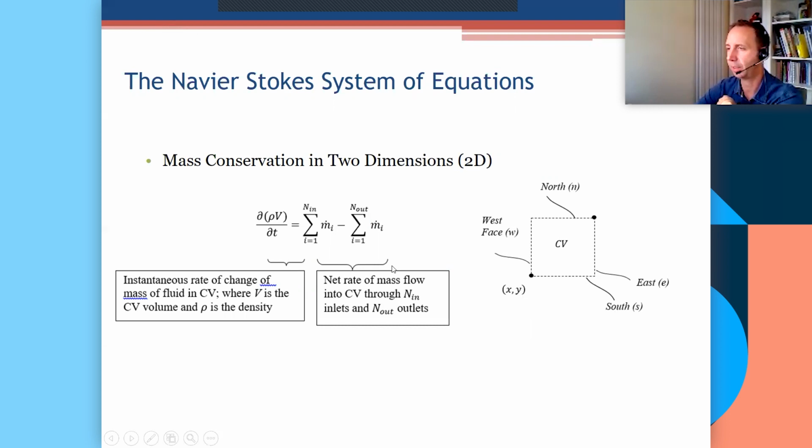So what does that mean? This is the sigma Greek letter, capital letter. It's used as a symbol to mean discrete summation. Discrete means you have a finite number of different variables that are summed, and the different variables are all written with an m and a dot on top and an increment i. So the increment goes from 1 to capital N_in. N_in stands for the number of inlets to a control volume. So we sum this quantity over all the inlets that may exist.